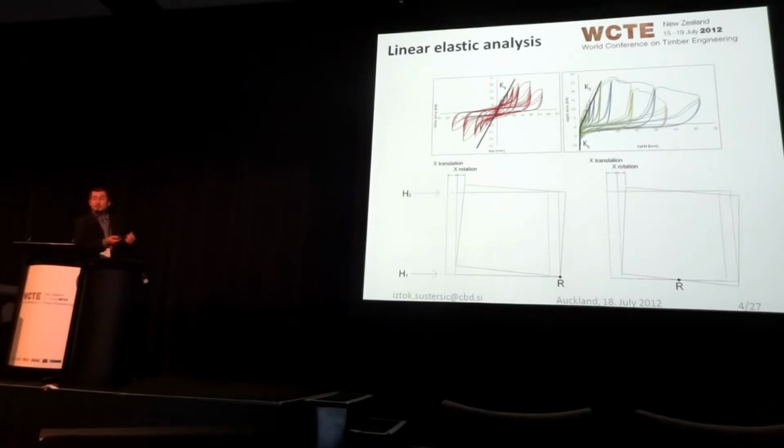And there's a difference. Even if you use a substitute stiffness for tension and substitute stiffness for compression, they are different. So if you want to model the connections with linear connectors, so basically with springs, you have to use bilinear elements. But bilinear elements cannot be used in the modal analysis, because you have to have one single matrix, therefore you have to have one single stiffness.